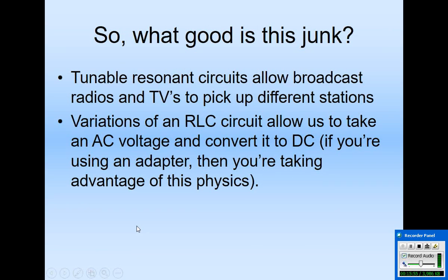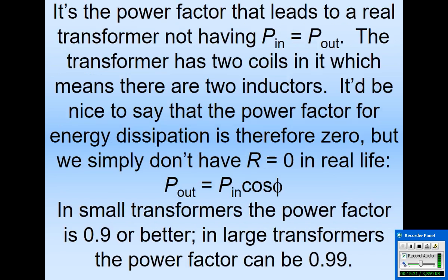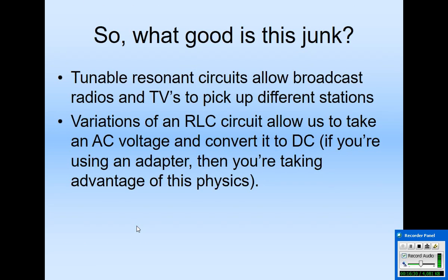So we see a real application in real transformers. We have to worry about those things. That's why electrical engineers make all this money trying to incorporate the right circuit design in order to maximize the power factor. There's always going to be an inductance inside a transformer, but if you can set up capacitors in just the right way, you might be able to achieve resonance. And at resonance with the effects of the capacitor canceling out the effects of the inductor, you can maximize the energy that is getting transferred from one to the other.